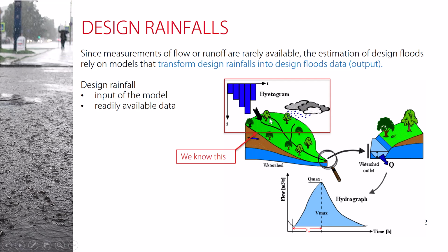So this is our catchment, which has its well-defined boundaries, and in hydrology and in all urban drainage system design, you will always be working with catchment boundaries. So you have to have a well-defined area, including the entire area that drains into a single point.